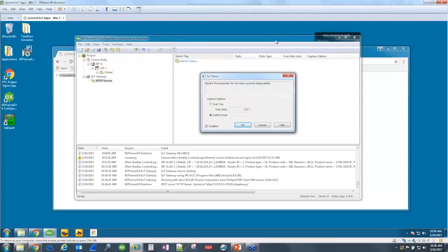My read URL is built with a simple syntax of read, a separator as a question mark, and then ID equals. I could take one of these data points or tag objects and issue a get directly to that tag object. And if I hadn't included the quotation mark in my tag, instead of getting a tag invalid, I would get a value. And there we go. There's the value. So as I refresh this page, I'm issuing gets. You can see that value hasn't changed.